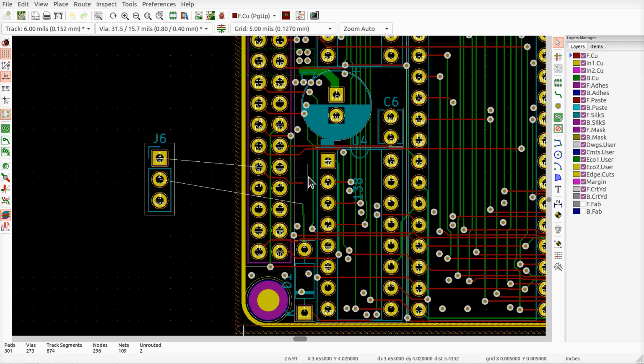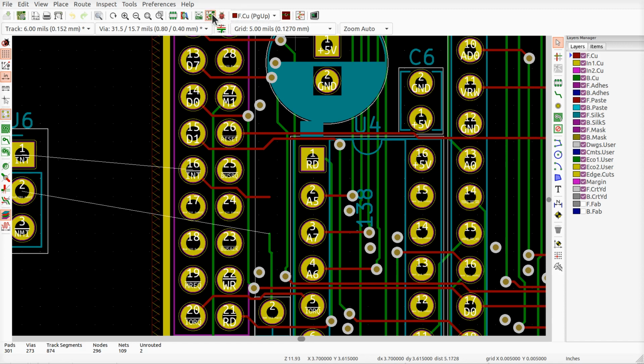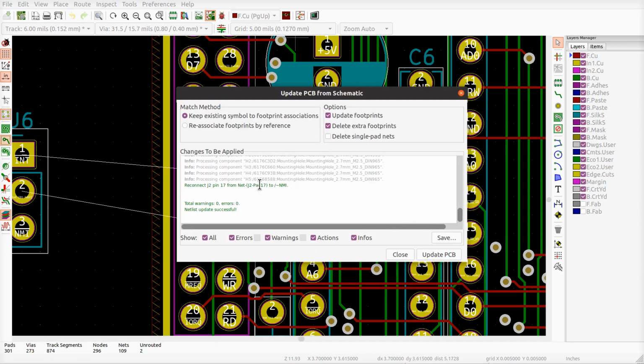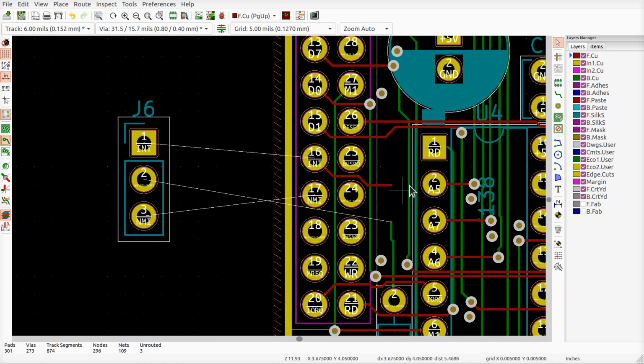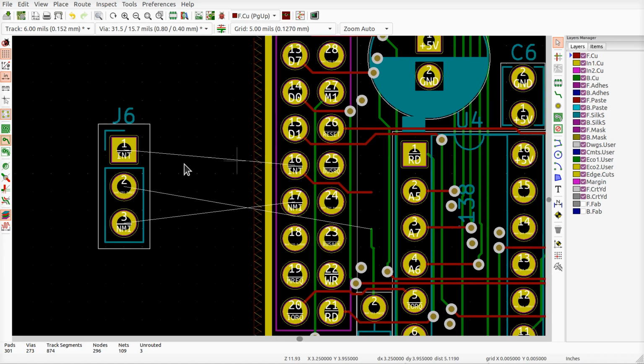All right, now, if we look closely and we import again, oh, someone just added a label to something that was previously not labeled. Okay, so now if we leave it in this orientation, we can run a track to the top one, track to the bottom one, and the middle one can snake around and out and come down here. You do not want to move this down here, because if you put it down there, you could jumper it to the middle, but you couldn't then jumper it up to here. This trace has to be in the middle, okay?